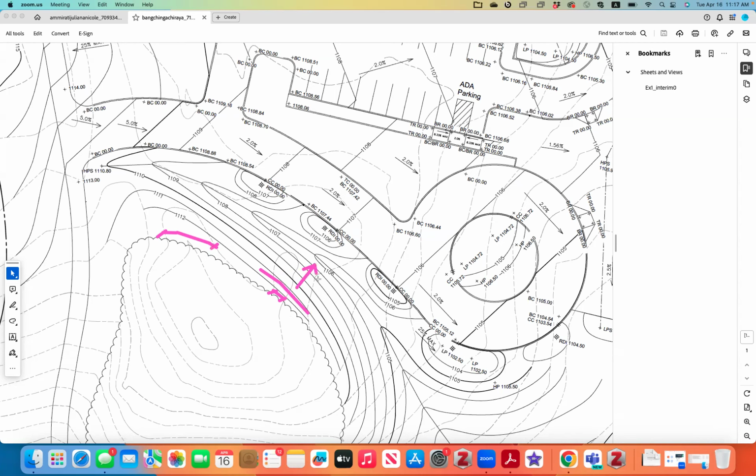So push this further by 4 feet. Yeah. And your divergence swale works. That shape looks great. To determine the slope of the swale, I need to have a distance between each point of the swale? Yes, these need to be the same. I would recommend looking through how many segments you have and just dividing them evenly. Then drag them up and down depending on how far away from the dividing point you are. Okay.